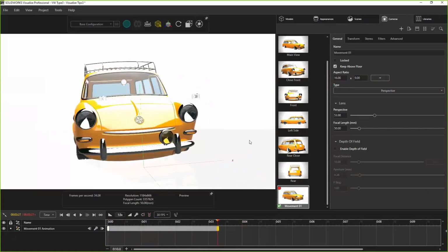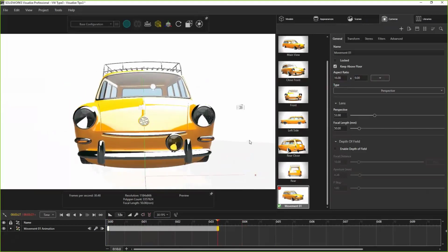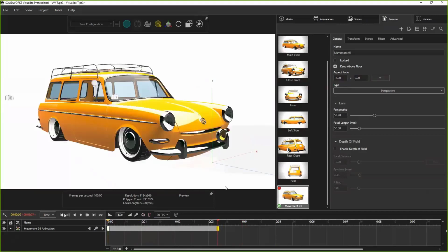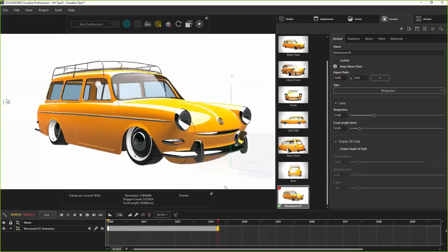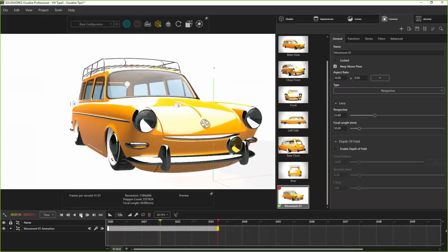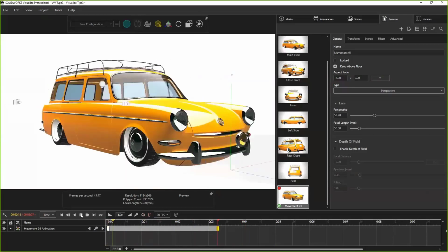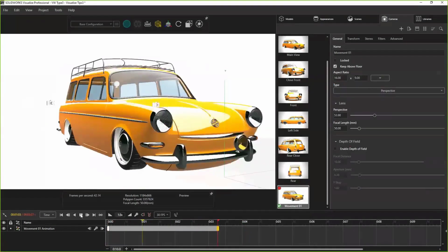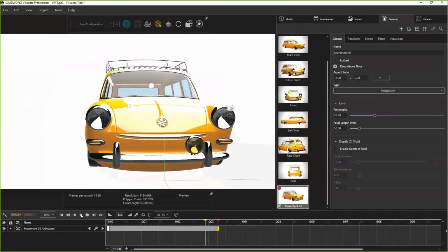So let's go ahead and reposition a little bit here. So for my final position, we wanted to end looking head on at the car, and then starting, we'll readjust our starting position. And now if I play that back, you see that it automatically updates those keyframes depending on where my position is on the timeline. Now we can also duplicate these spots.